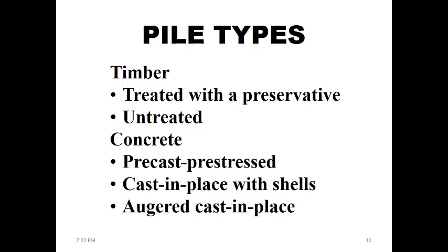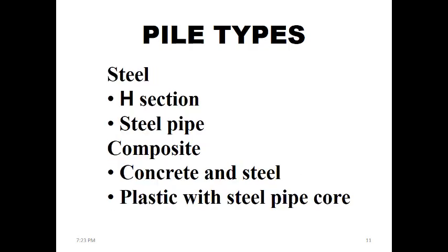Well, it will occur due to detonation of explosives that you will place after drilling down the hole. So there will be some charge in there and it will compact the soil around it, which will increase the volume like a ball or bubble that you can think of at the bottom part of the drilled hole in the soil. And then when it's filled with concrete, it will create a footing in there that will support the loads from the pile.